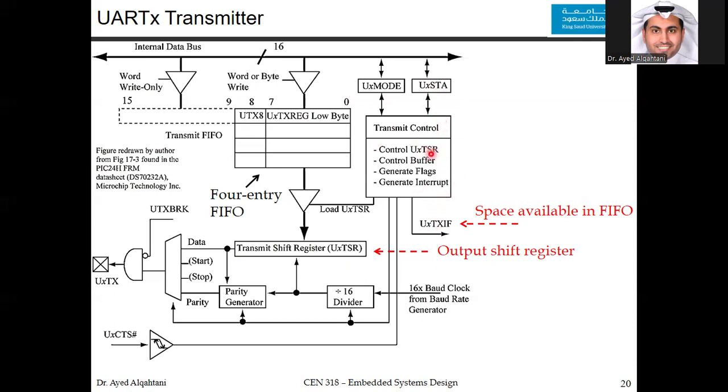That's the transmit control. It has other functionalities as well, like these buffers that you see here. In this queue, it could be only from 0 to 7. You can make it from 0 to 15. So here in this buffer, either you choose word or byte. There is a choice. Either you use only byte or the whole word. And this buffer only if you use a word. If you use from 0 to 15, then you will supply the data over here for the FIFO.